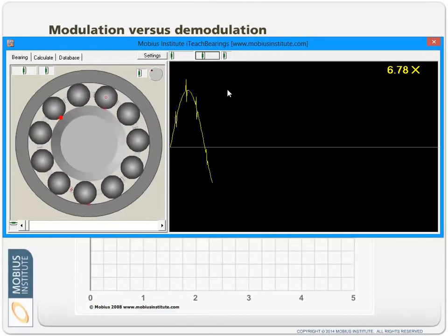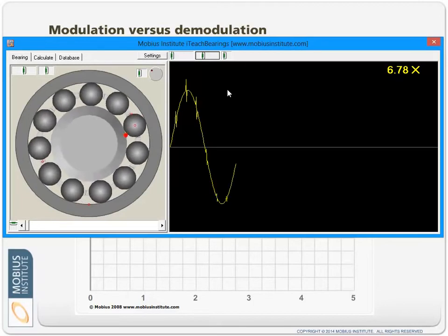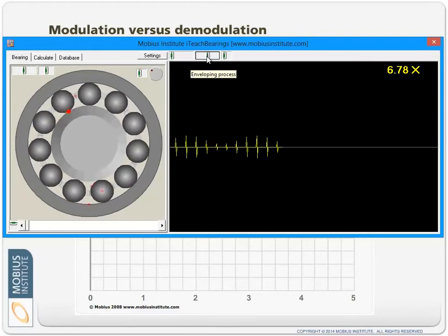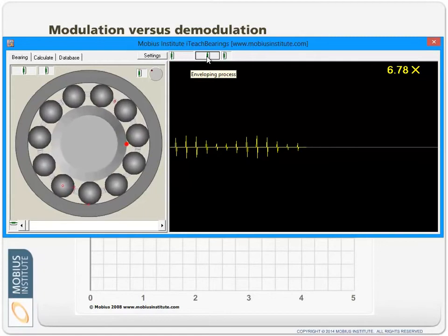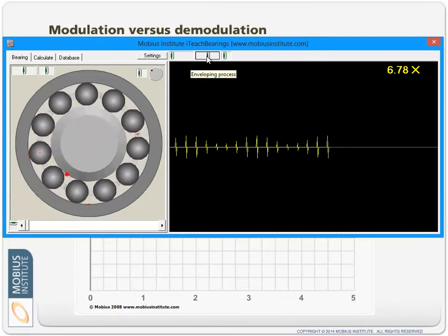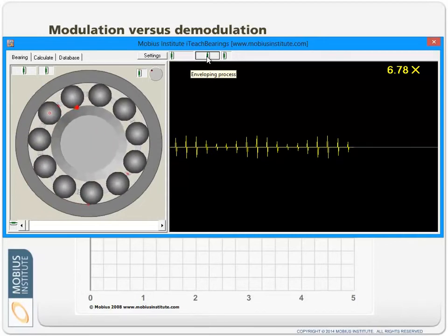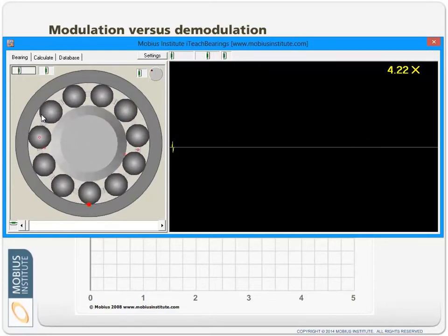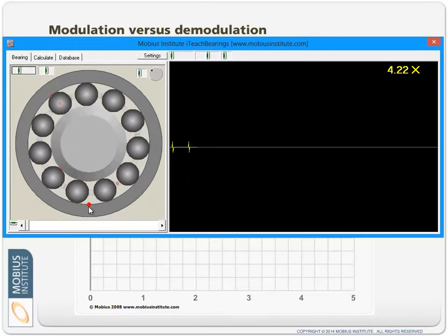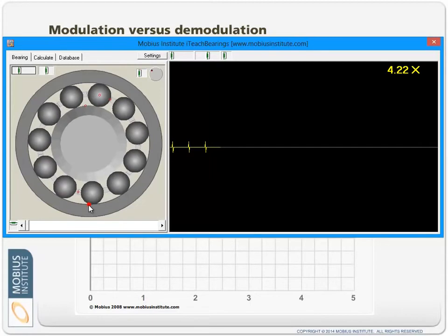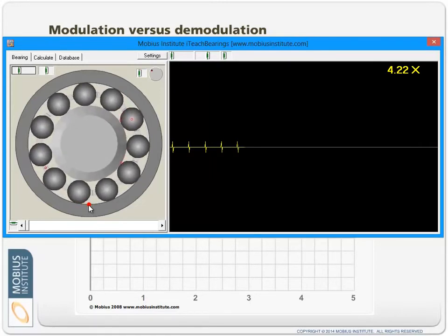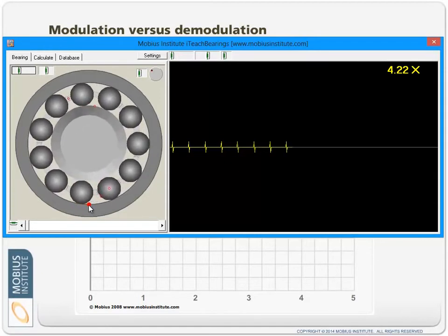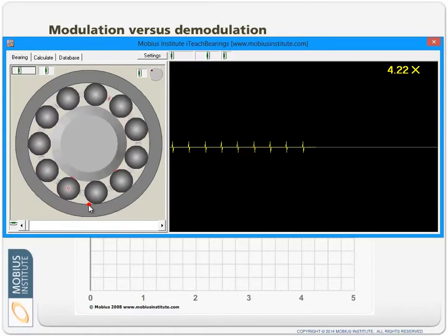Step one of the smart technology is to filter out all that low frequency, high amplitude vibration. Now, it's potentially a little misleading what I just did then, because there are two things kind of going on. There is just a periodic source of vibration, but every time there's an impact here, so every time there's this damage on the inner race or on the outer race, let's not confuse these sources of modulation. Every time I get this little ping, there is a sound. Ping, I'm waiting for it, ping, waiting for it, ping, and that's something that if the amplitude was higher, we might pick up in a normal spectrum. But every time we get a ping, something else happens inside the machine.